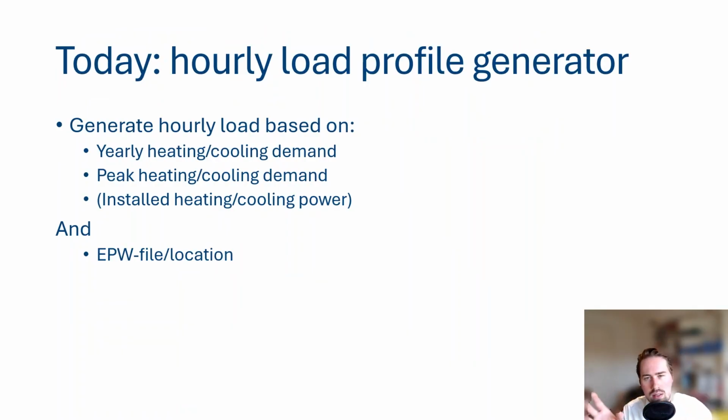Now, typically, as we discussed earlier, hourly loads are created based on dynamic simulations where you need quite a lot of building information, you need a 3D model, and it's very time consuming and very costly. Now, we created a method for you that you can actually create an hourly load profile based on just an estimation of the yearly heating and cooling demand, which you always have to do.